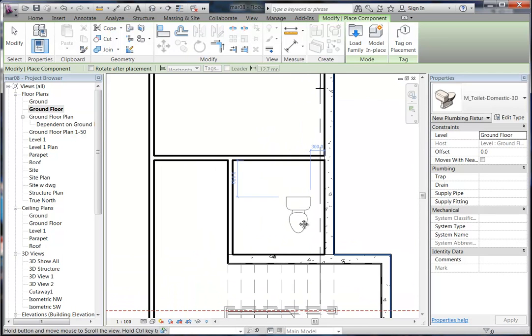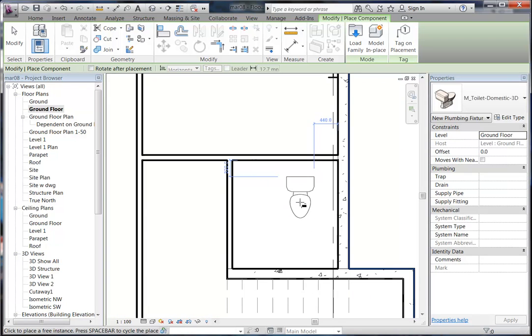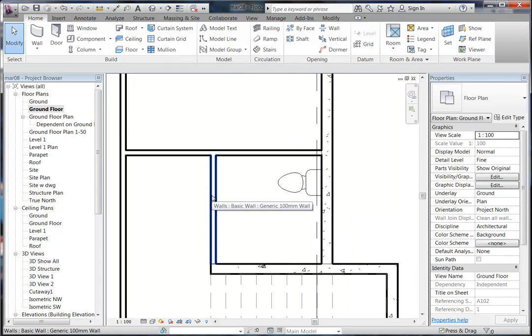So if you've got to have a unisex disabled, that would be perfect. That's basically the size of a unisex disabled. I can just tell looking at it. Okay, so something like this, and then that'll give you room for the handrail and everything you need on the wall. And sliders, you probably worked this out already, sliding doors for unisex disabled are definitely the way to go.